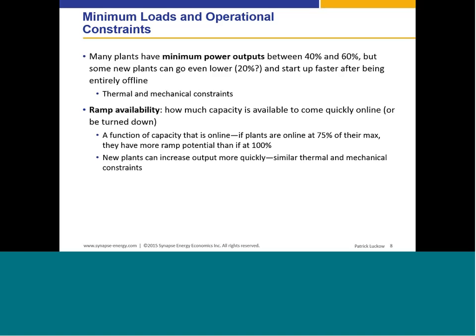The other major issue is ramping availability, both upwards and downwards. We need sufficient capacity that can increase its output at a rapid rate. The timing of that rate varies. We could be talking about as little as 5 or 10 minutes, or it could be an hour ramp or a 3-hour ramp, which is kind of what we were looking at on the previous slide, where you have a few hours when you know the solar generation is going to drop and you have to balance that.